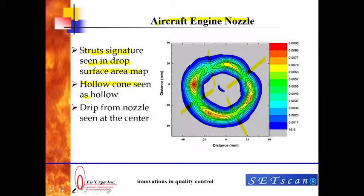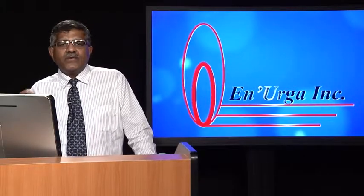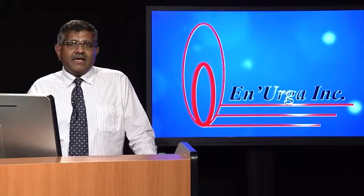The second thing that you can see is that a hollow cone nozzle is always seen as hollow. For example, here you can see the hollow cone nozzle; in the middle you have 0 surface area density. And finally, there was a small drip in this nozzle at the center. The small drip is very small, and we were still able to pick that up. So, it shows you how reliable and extremely accurate the entire system is, that it can show you small drips, small signatures of struts, where the peak intensities are, and where the lowest values of intensities are.